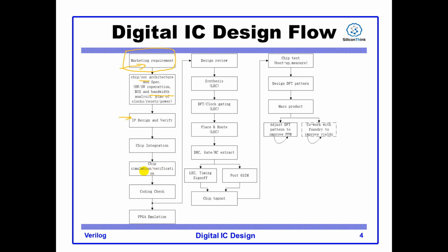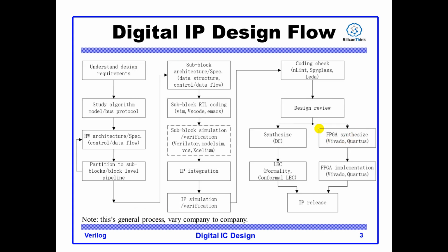And you will do simulation and verification. Also the coding check, using lint tools such as Spyglass. At this point, the design process will be divided into two threads, the FPGA emulation thread and the IC design thread. So the FPGA emulation thread is something similar to what we have talked about here.